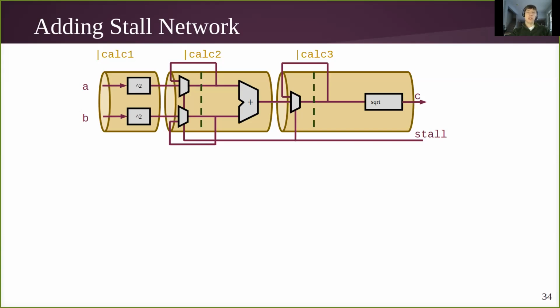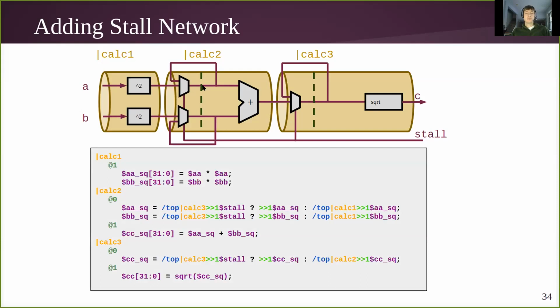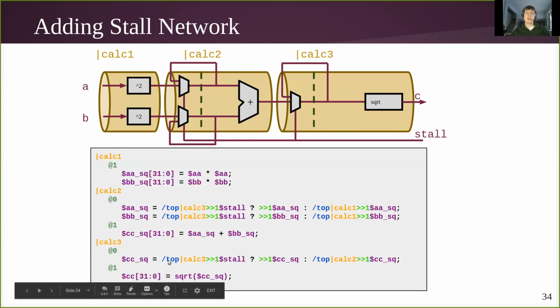So now we have these mini sort of degenerate pipelines. And we no longer have to draw our flops explicitly. Where I've recirculated the values outside of the pipeline context, there's no implied flip-flop. Where they're crossing stage boundaries inside the pipeline, that implies a flip-flop. So literally taking this diagram and expressing it in logic, you would end up with this.